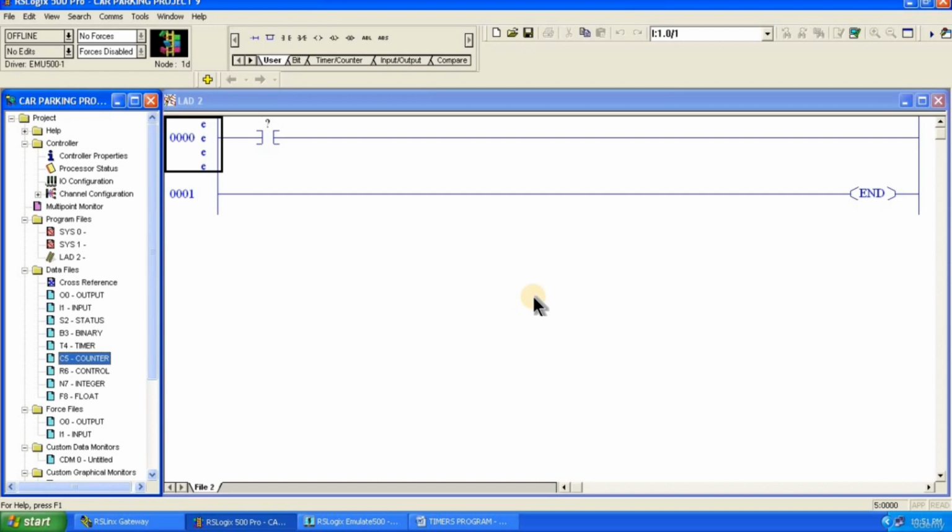In the previous session, we discussed that we don't need to put the value of the accumulator in the up counter. Whatever value the counter counts in the online mode will be the accumulator value in the up counter. But in the case of the down counter, you can observe something different. The name itself indicates what the down counter means: it counts in a decremental order, meaning there will be a countdown operation.